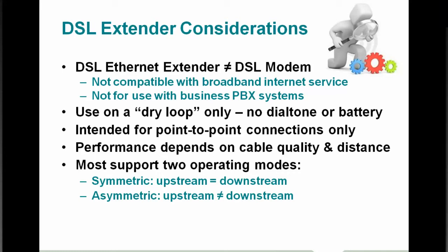I think in most applications, you're probably going to need to characterize what the usage is. Is it simple SCADA usage, where you're going to have that plus maybe some engineering access for remote diagnostics, which is maybe a little closer to a symmetric application for balancing it? Or are you going to have a heavy load going in one direction, such as in the case of having IP video surveillance being used in a system, right?